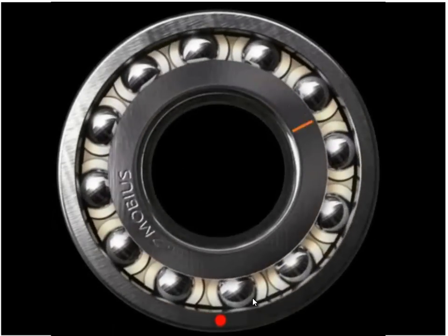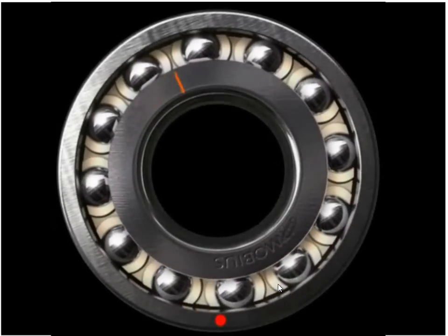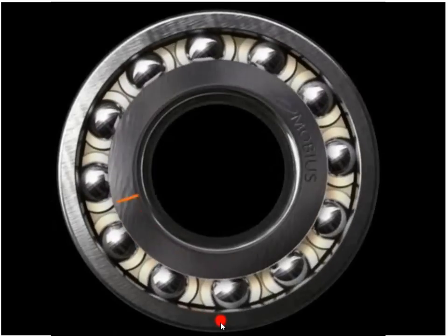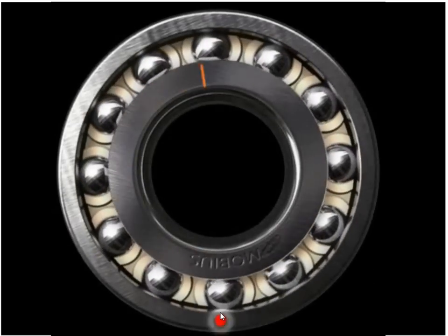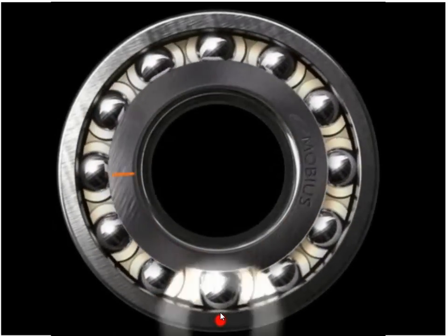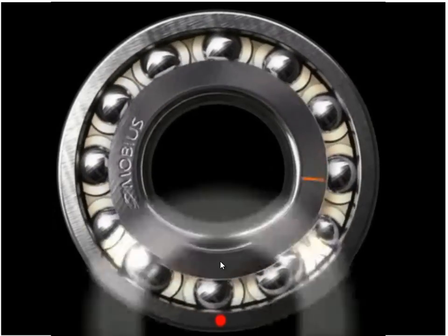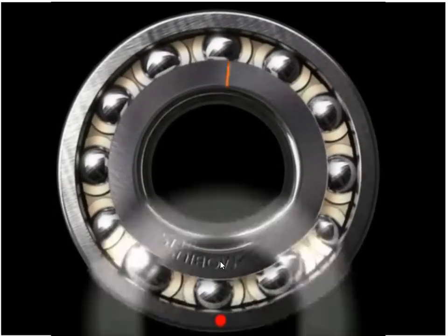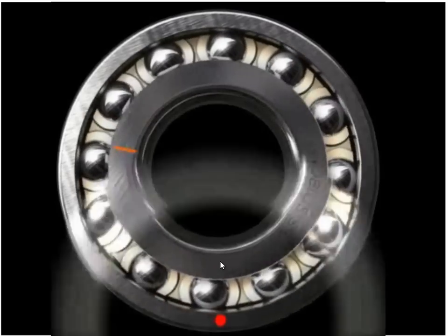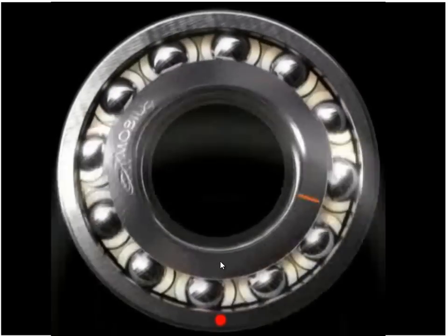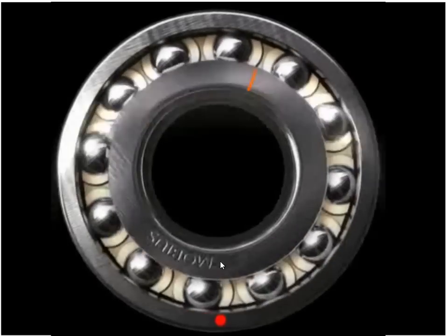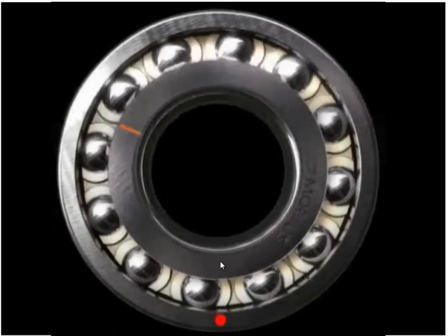while the rolling elements are not making contact with that point, there is no vibration. But when the rolling elements come along and make contact with the spall or the crack or whatever is sitting there, we get an impact, and you can see these white waves rushing out. That's called stress waves or shock pulses. If you take any two metallic objects and clack them together, you put a little short stress wave through those two items, and we can detect that.